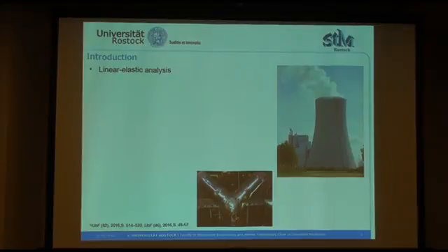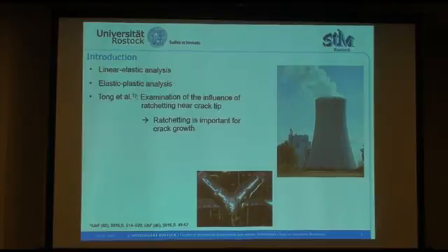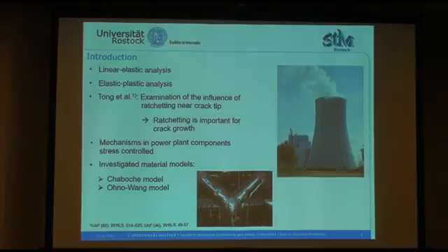First investigations were made already using linear elastic fracture mechanics. But to enter these results, it is necessary to do also elastic plastic simulations. In that case, there are examinations of the influence of ratcheting in the crack tip by, for example, Tom et al. These examinations have shown that ratcheting is important for crack growth, and because mechanisms in power plant components are stress controlled, it is necessary to find a material model that describes ratcheting behavior correctly.